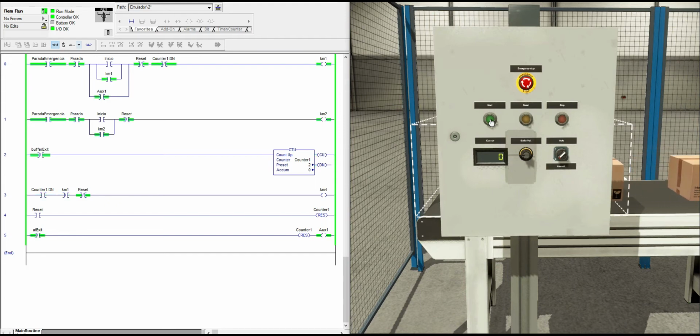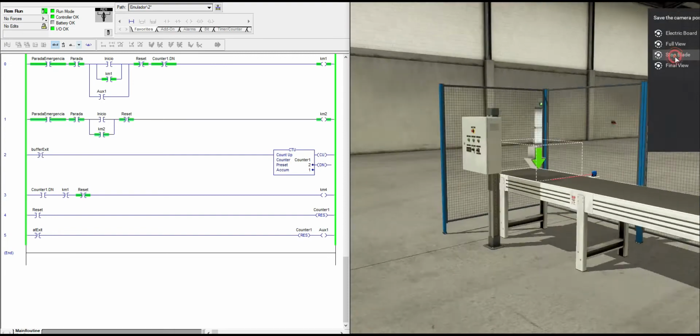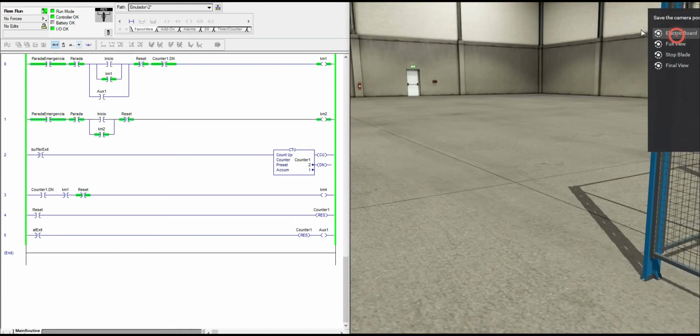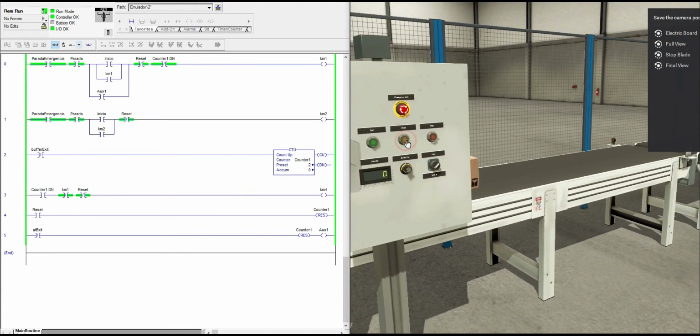When it reaches the count, it stops the KN1 output, which refers to the first conveyor belt. Then the logic waits for the activation of the second sensor, which will activate the transport processes again. Let's see how our reset button works a bit, which takes all the processes of our logic to a start, where the counter is at 0 and the conveyors are off.